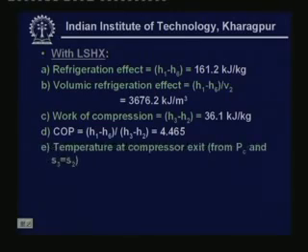Then the temperature at compressor exit, we find this from the pressure and the entropy values. You find that it is almost 105 degrees centigrade, it is 104.9 degrees centigrade. So, this is the performance with the liquid suction heat exchanger. Now, let us find out the performance without the liquid suction heat exchanger. Again, what we do is we apply the energy balance across the evaporator, compressor, condenser, etc., and then find out the required parameters.